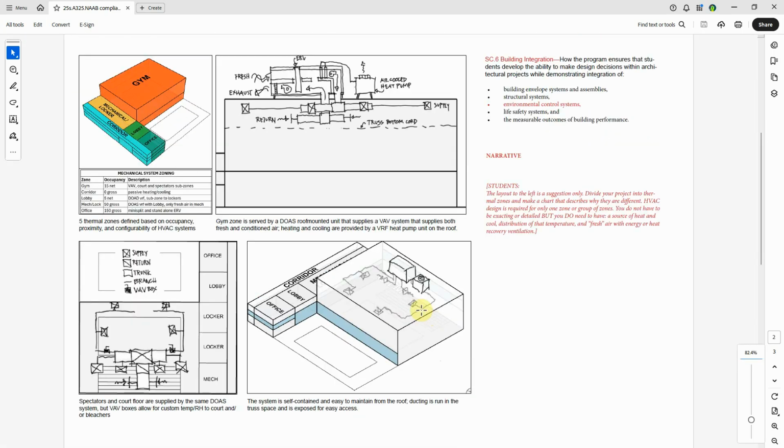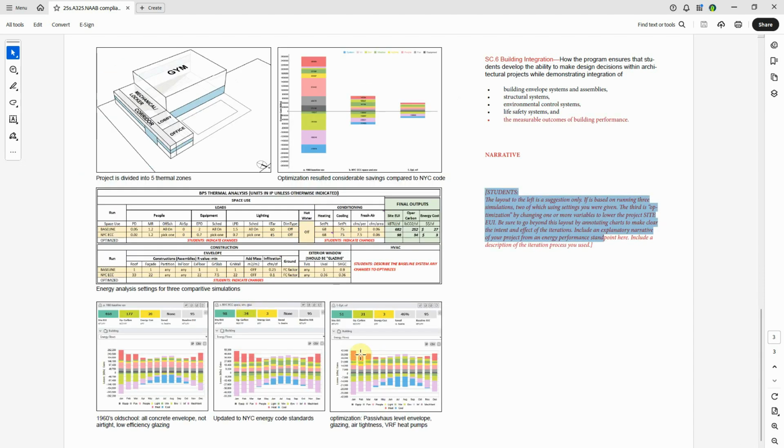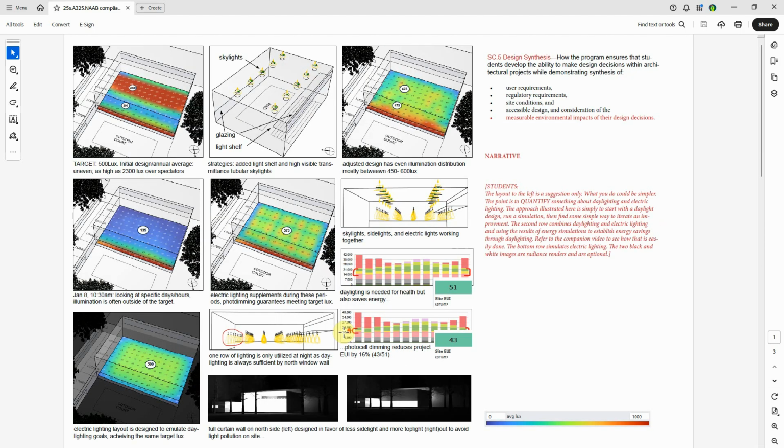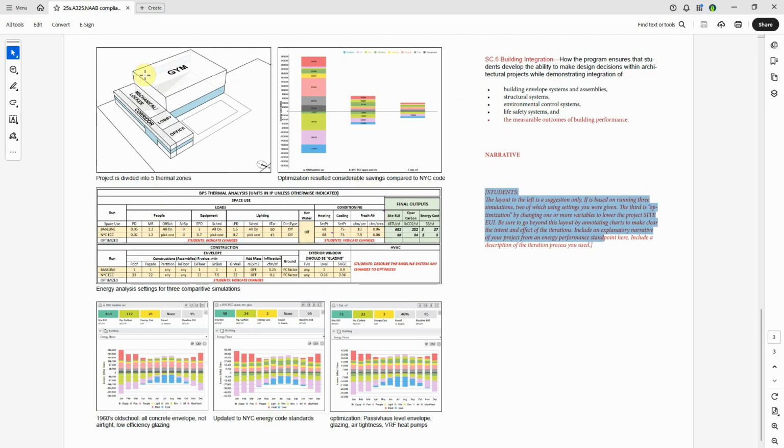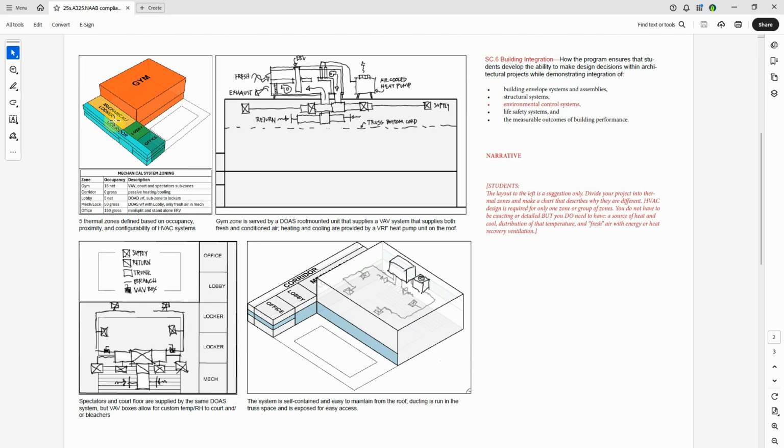We basically have this one done now because we said we already did this, and it's based on the same geometry, at least. It may not be the same zones because you can define yours. How should I put this? In your thermal model, you can make every single room a zone, and if you give it the same settings, it makes it just like one big zone. Whereas what we're saying here is that if we really had an engineer designing this, these would have different requirements for the HVAC system, and that's what we're defining here.